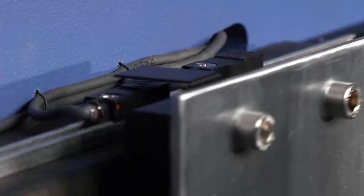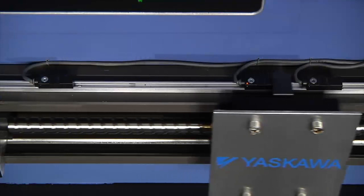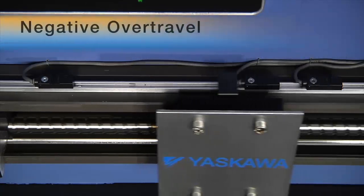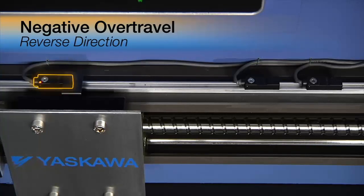Overtravel inputs can prevent costly damage. Without it, moving parts of the machine could be allowed to crash into one another. Now, the positive overtravel sensor is connected to the amplifier input that stops motion in only the forward direction. The negative overtravel sensor is connected to the amplifier input that stops motion in only the reverse direction. So you can see that if these sensors get switched around, or if the direction of the servo doesn't match the direction of the machine, the motor might not stop at the overtravel sensor.